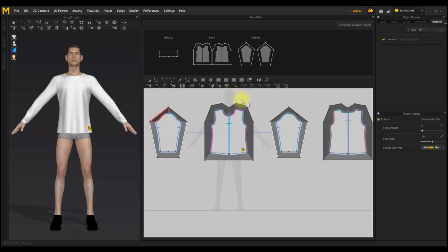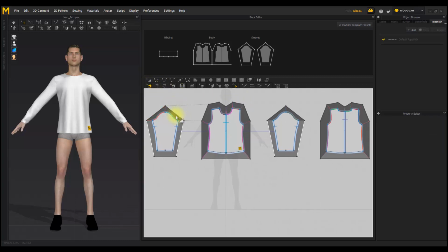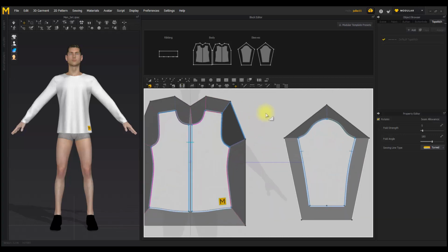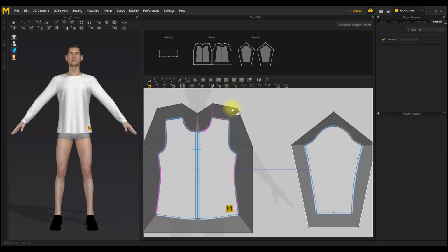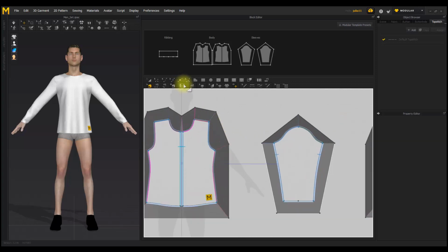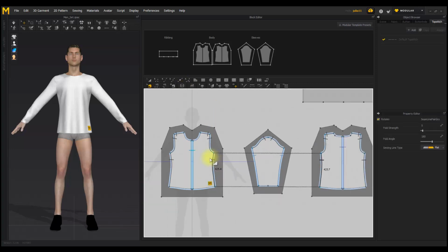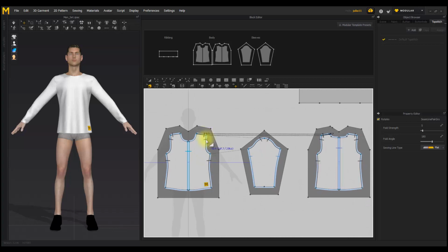You can use the Edit Sewing tool to view and modify seams. After sewing blocks and patterns, turn on the Show Modular Sewing or Show Pattern Sewing tool and, if the Edit Sewing tool is selected, you can see the sewing lines between the blocks and the pattern. Even if blocks and patterns are sewn, if you select the Edit Sewing tool with the Show Modular Sewing or Show Pattern Sewing tool turned off, the patterns will be displayed as if they were not sewn. This makes it easier for users to see where the patterns in the block are sewn because the block and pattern are connected by a sewing line.